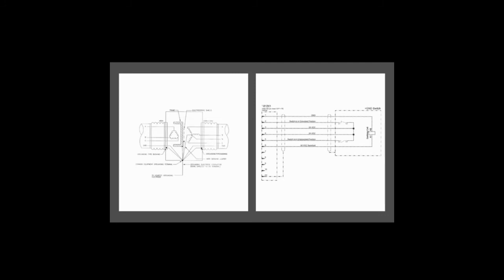From the laboratory, we managed to understand that this ground system consists of a copper braid, switch, grounding chamber and ground rod to ensure the safety of the system circuit. The grounding system must be at very low potential, which requires low resistance. Based on the regulation it must be below 2 ohm. But referring to IEEE, if the resistance is lower than 5 ohm for the utility testing, it should be acceptable. We learned that the laboratory grounding system cannot be connected with other buildings, to maintain the grounding resistance and for safety reasons.